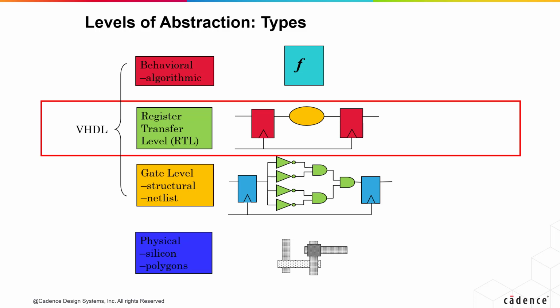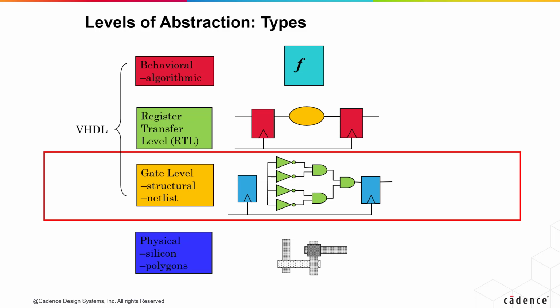2. The register transfer level, RTL. Here, we partition the system into combinational and sequential logic, using constructs and coding styles supported by logic synthesis, and it has one or more explicit clocks. You define timing in terms of cycles based upon one or more defined clocks. All operations are scheduled to occur in specific clock cycles. However, there are no delays below the cycle level. RTL is the input to the synthesis.